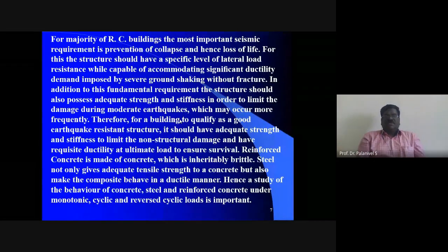For the majority of buildings, the most important seismic requirement is prevention of collapse and hence loss of life. For this, the structure should have a specified level of lateral load resistance while being capable of accommodating significant ductility demand imposed by the severe ground shaking without fracture. In addition to this fundamental requirement, the structure should also possess adequate strength and stiffness in order to limit the damage during moderate earthquakes, which may occur more frequently.